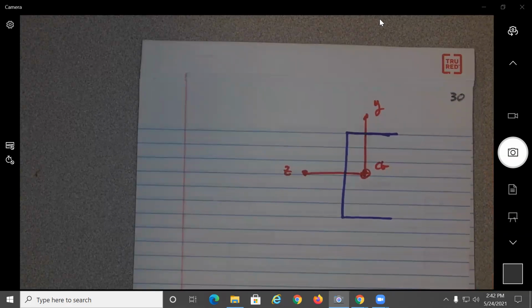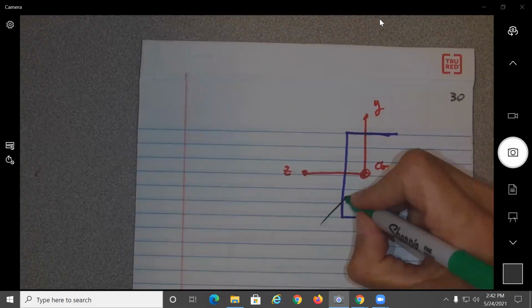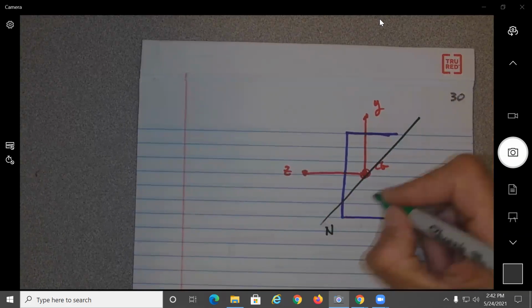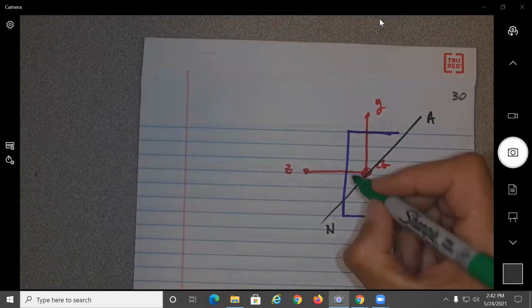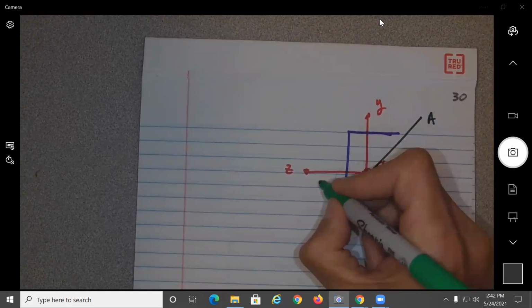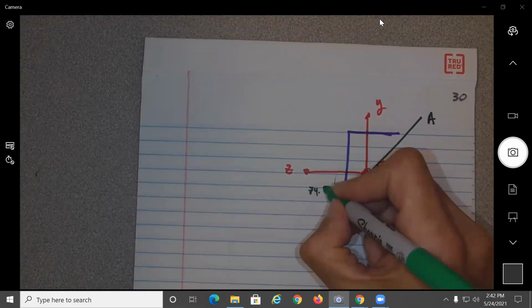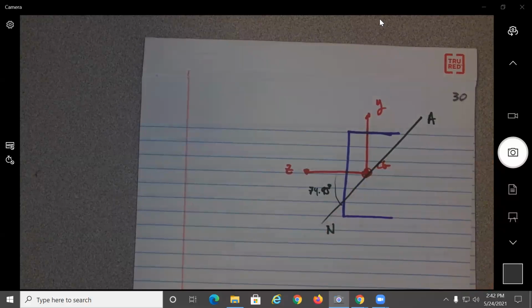The neutral axis will be at an angle of 74.95 degrees in that direction. I don't know where it's going to cut, but the stresses would probably be 0 here and 0 over here. No, it should cut. This is almost 80, so it probably goes more up and down. I guess it will be here and here somewhere on the two flanges, the bending stresses will be 0, no? Yeah, because that's the definition of the neutral axis. But obviously I did not plot it properly.